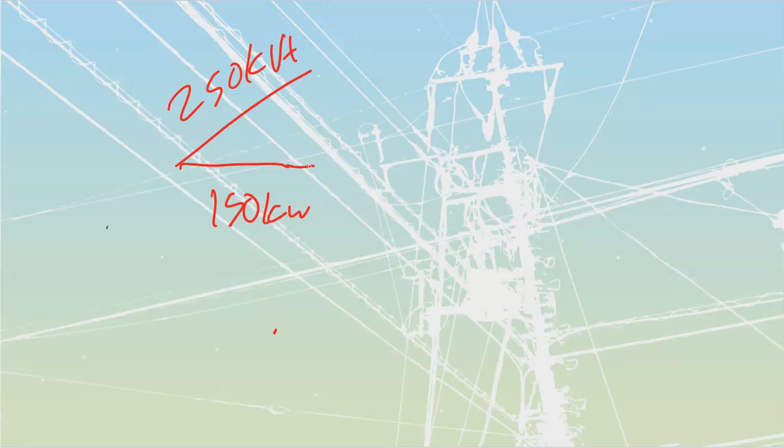What we don't have is a barometer, something that's going to measure our vars. All of our vars, even on power quality meters, are always a calculated value based off the difference between my watts and my VA. We're going to calculate this one for what we would need to get to unity. There are two ways that we can go about calculating that.